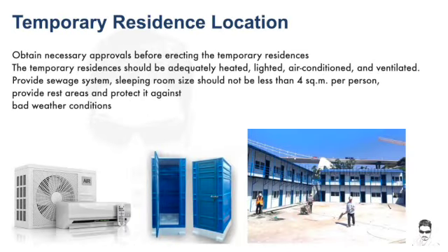Obtain necessary approvals before erecting the temporary residences. The temporary residences should be adequately heated, lighted, air-conditioned and ventilated. Provide sewage system. Sleeping room size should not be less than 4 square meter per person. Provide rest areas and protect it against bad weather conditions.